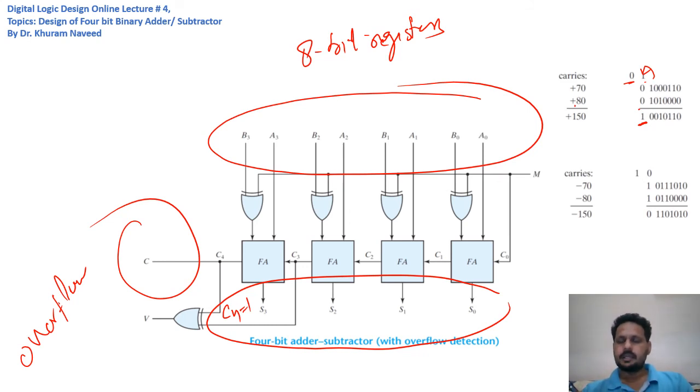Or in the situation where the carry from the previous addition is 0, but since the two sign bits are 1, because of their addition the sum is always 0, and the carry at the next location now serves as the sign bit, right?